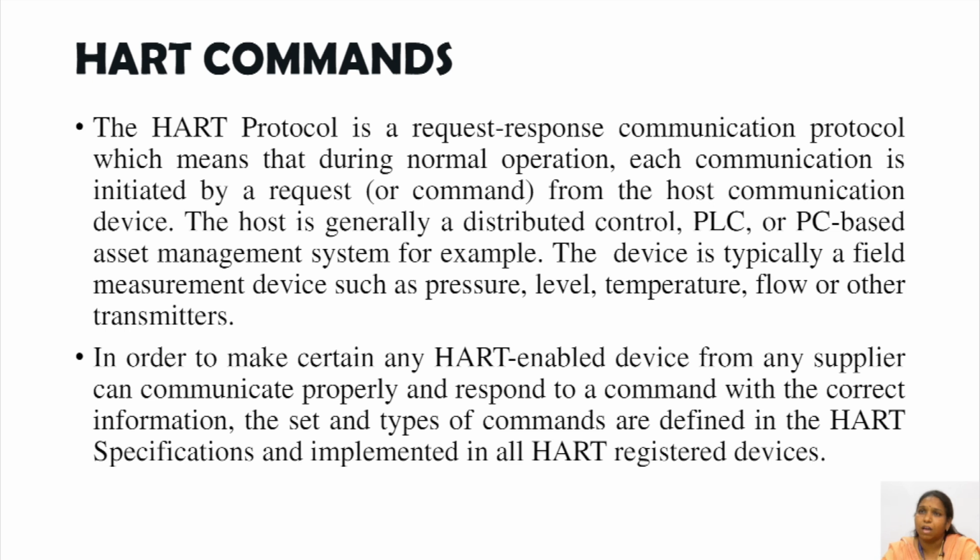HART commands. The HART protocol is a request response communication protocol, which means that during normal operation each communication is initiated by a request from the host communication device. The host is generally a distributed control system, a PLC or a PC based asset management system. The device is typically a field measurement device such as a pressure, level, temperature, flow or other transmitter.